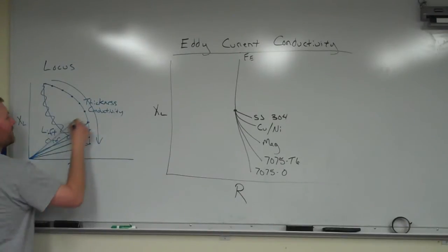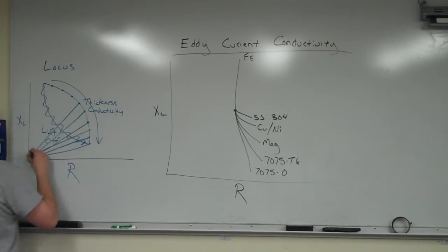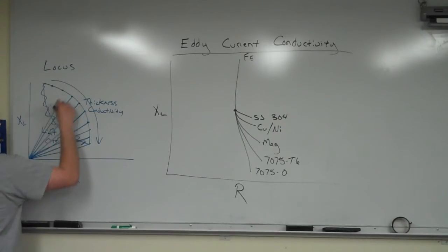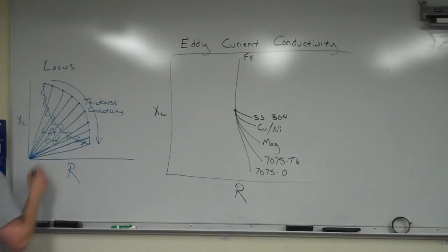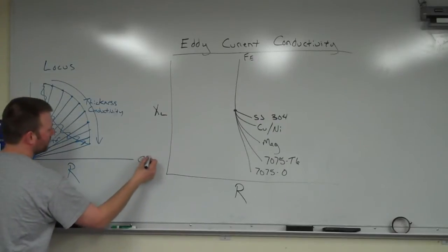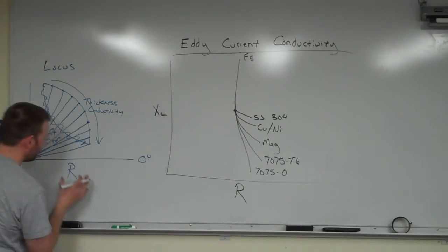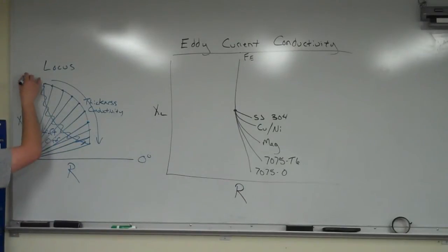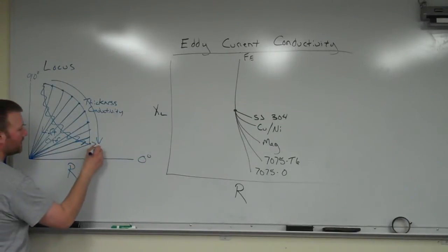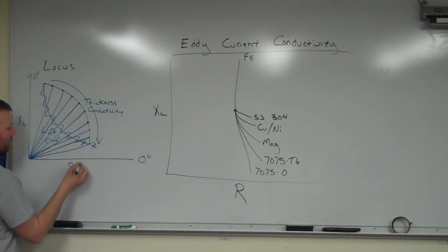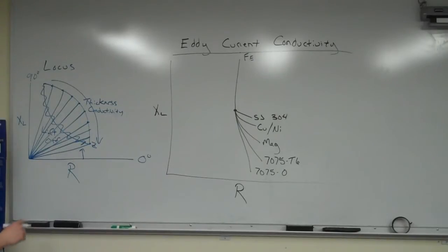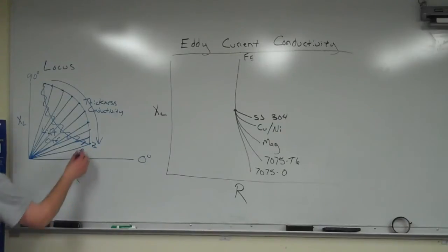That impedance is made up of inductive reactance and resistance, but we're basing everything from this bottom left corner. If we were measuring resistance in a circuit carrying only resistance, phase lag is 0. In a circuit carrying only inductive reactance, phase lag is 90. So any one of these impedance points is going to have some amount of phase lag.